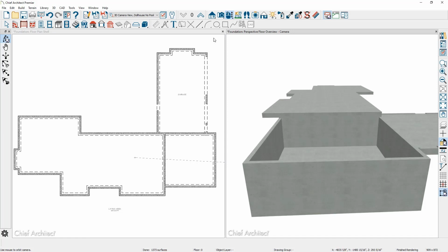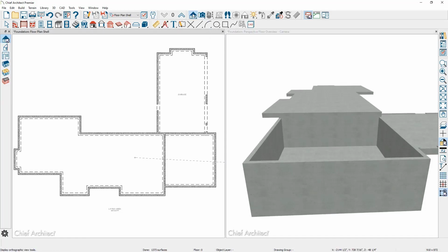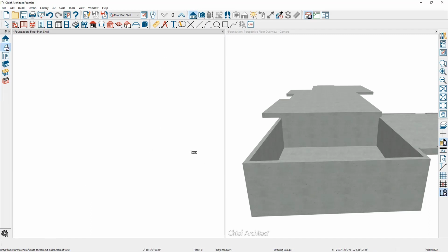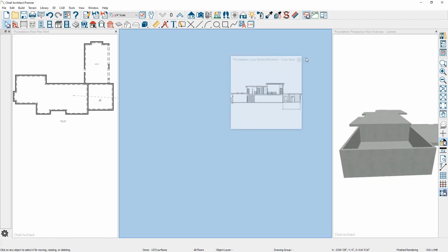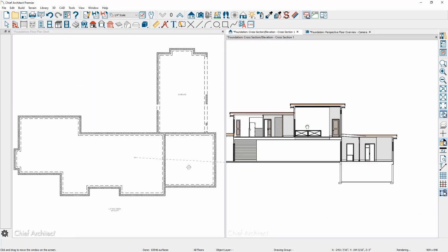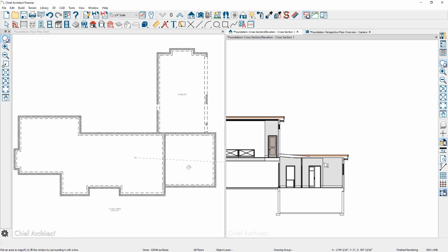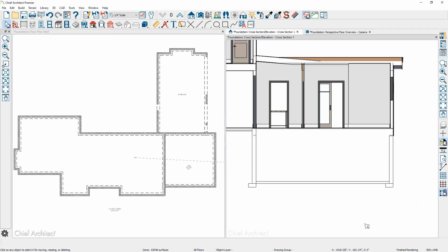To do that, I'm going to move over into the floor plan view. Let's use our cross-section camera view. Actually, the back clip. We'll slide the clip through the area. I'm going to pull this view over, and let's just slide that over here, and then use the zoom tool so we can see exactly what we're talking about for the foundation. You can see the walls have an offset for the footing. Let's begin there and center the footing.